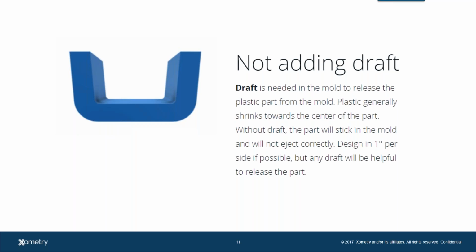And by the way, this is the number one thing I will give feedback on if you do submit your design for injection molding. Usually we are going to catch edges that don't have drafting that require it. At a minimum, we look for 1%.